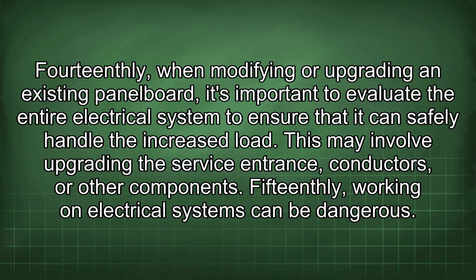14thly, when modifying or upgrading an existing panel board, it's important to evaluate the entire electrical system to ensure that it can safely handle the increased load. This may involve upgrading the service entrance, conductors, or other components.